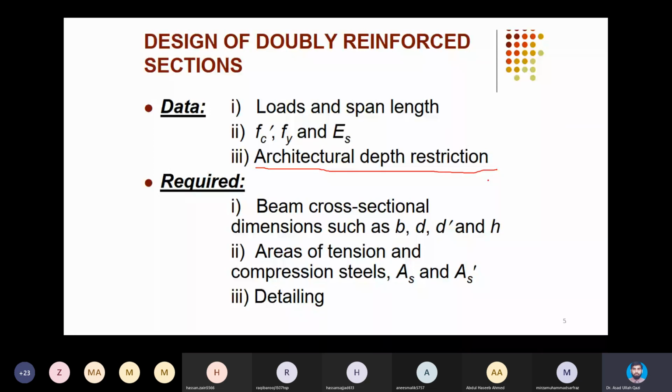So obviously I will not be allowed to go for an over reinforced singly beam. I will then prefer to design a shallow doubly beam. And once you are given the architecture working drawings and you decide what type of slabs there will be, whether they are one-way slabs or two-way slabs, depending upon the aspect ratio, and finally you decide the provision of beams, whether beams will be only present on the column center lines, or you will also provide some secondary beams, and you will divide the big panels into smaller ones.